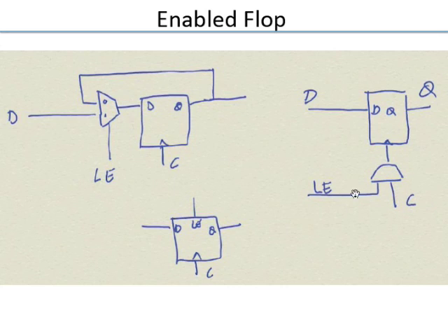The benefit of this approach is that when I'm not loading this flop, I don't have any transitions here. So power is less. Whereas here, my clock will always keep on toggling, so I'll have more power consumption here.